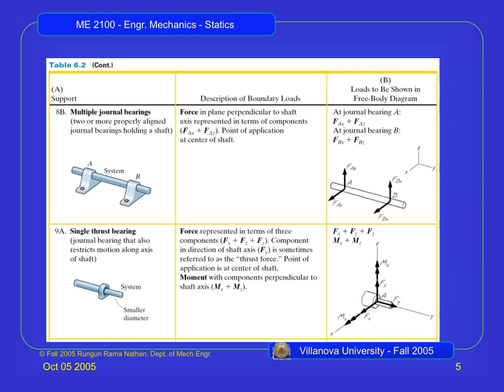And then this is a system of two of those, right? Okay, a system of two of these. So again, what can this one do? It can rotate this way, and it can slide back and forth this way. But if I have those forces alone, it tells me I can't rotate this way, because again, visualize, fix both of them here. If it's fixed in one spot, maybe it can rotate, we don't really know, but in the previous diagram we saw it couldn't because it was a collar. As soon as it's fixed in two spots, it's assumed it can't rotate. You know it cannot rotate this way, so you don't have to show those moments in this diagram. Okay, it's similar to the last one in that sense.